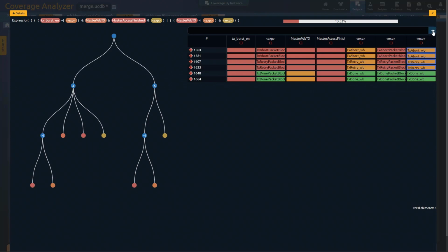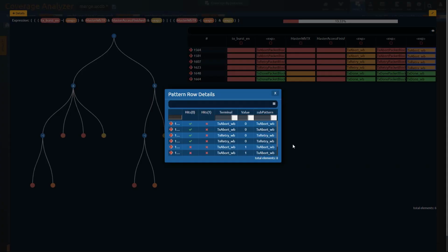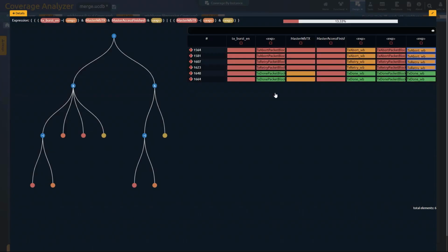being covered. Here I'm looking again at all of those expressions together, and what you can immediately see is that all 4 of them are presenting a value of 0, but none of them are ever presenting a value of 1. And so that's clearly why this particular term is not being covered. If we take that expression and look at where it resides in the expression tree over here, you'll see that it actually goes into an AND operation.